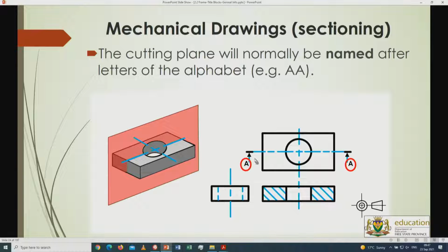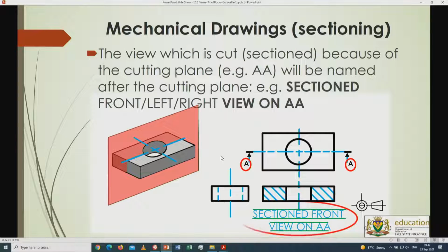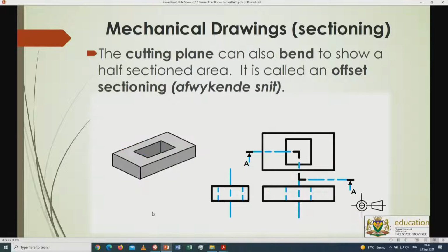Also, again, the direction of the arrow is important because you look at it from this way, third angle, and place it over here, also important. And that is a sectional front view. So many times learners forget about the section part, the section front view, because it's sectioned over there and it's sectioned over there. So that's what you see in that regard.